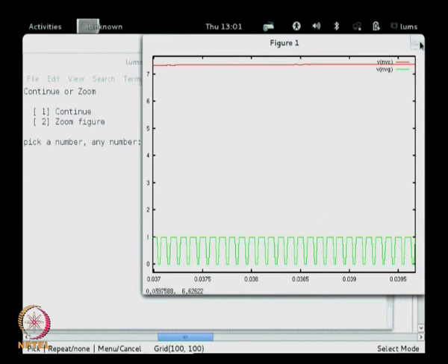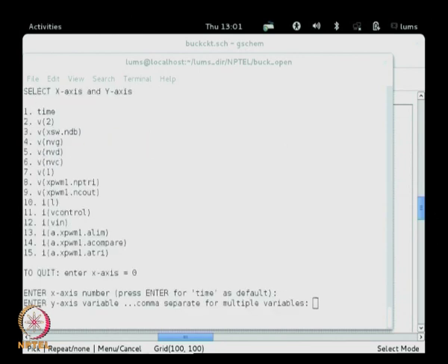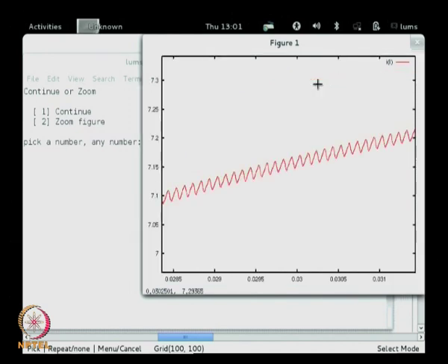And if you would like to see the waveform of the inductor current IL, though it shows smooth, when you zoom in and open it out, you will see the triangular wave shape of the inductor current of the buck, just like we see in a regular buck converter, up and down in the triangle fashion. Okay, this is the open loop system,